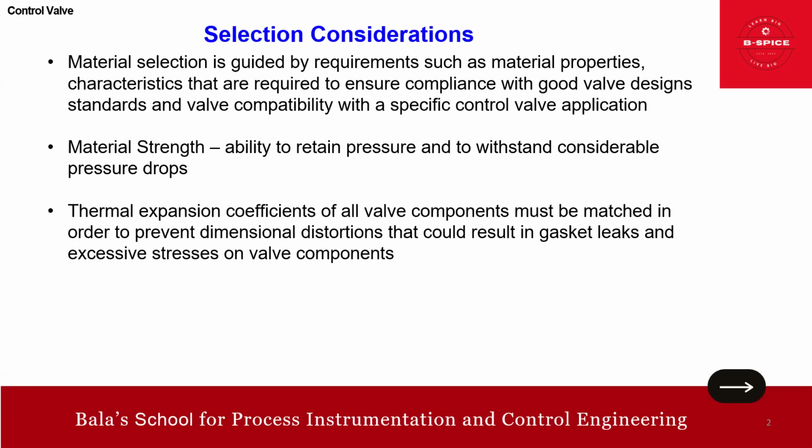Then additionally, we also need to focus on the thermal expansion coefficient. Basically, the thermal expansion coefficient of valve components must be matched in order to prevent the dimensional distortion that could result in gasket leak and excessive stresses on the valve components. So this is a second item, the thermal expansion coefficient, which for all components must be matched.